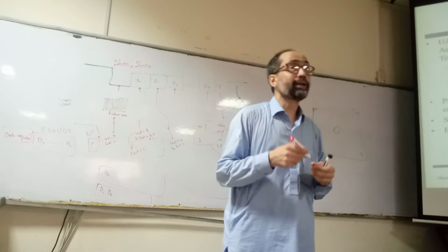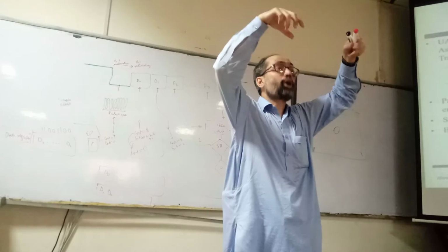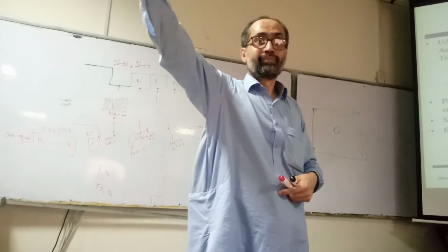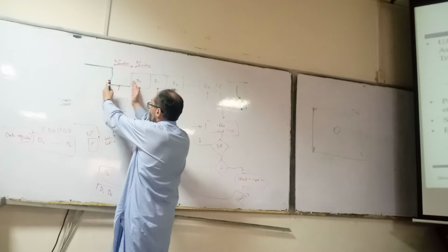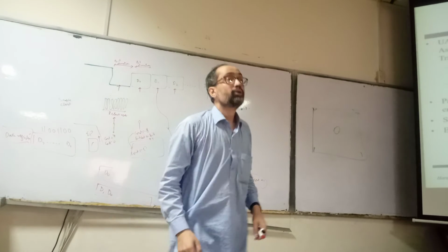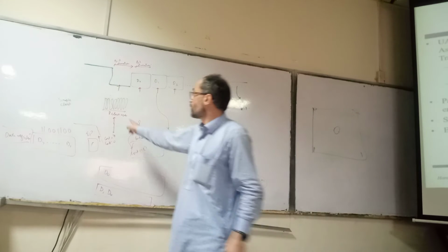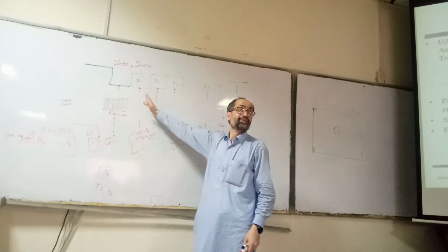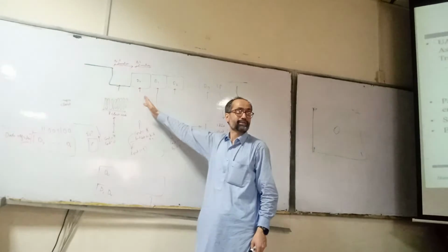So actually, if you look at the design of the receiver, the receiver is receiving the data serially. It has a sample clock that runs faster than the input frequency, whose frequency is higher than the input frequency. Now let's assume in 1 bit duration, the number of sample clock cycles is 24. So to reach the middle, how many clock cycles do we require? 12. And to reach the middle of the next bit, we need 24 clock cycles.